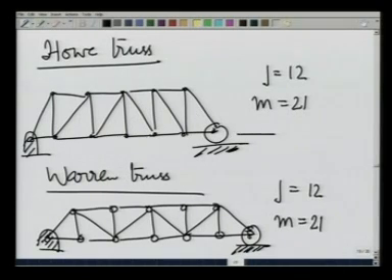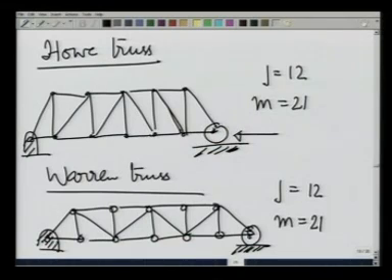Why we put a wheel or a roller here is because what we have assumed in all this is that these members are rigid members. However, in reality they deform, and when they deform, the distances may change, and to accommodate for that you put a roller here rather than a fixed pin joint, so that stresses are not developed in these members.